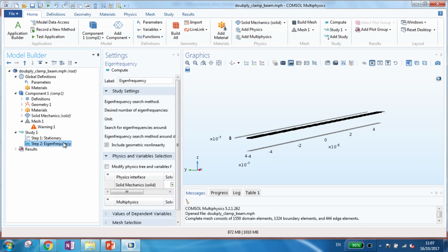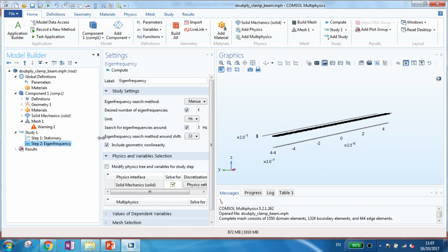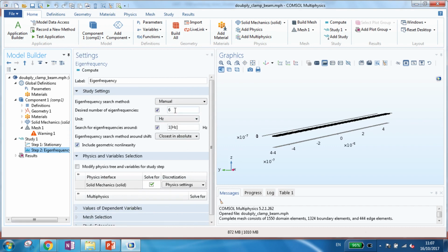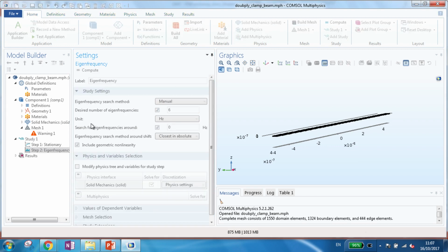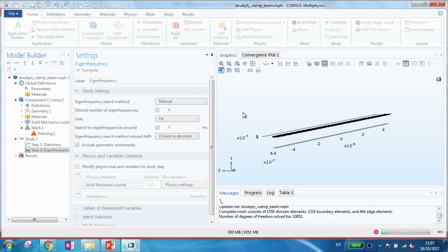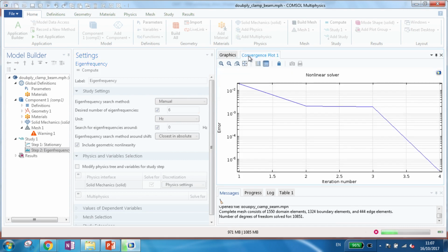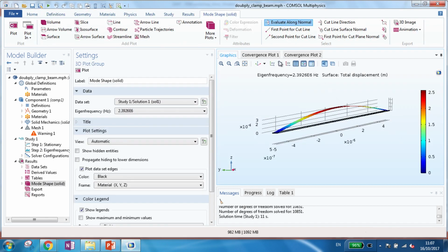results. So I just hit the simulation. You do the same thing. So now if you look, there are two solvers. First would be the nonlinear solver. It reached. So if you look at the convergence plots, guys, here, the one convergence plot will be for the nonlinear solver. It's reached. Then it starts the convergence on the second, which is the eigenmode solver. And it uses the values calculated for the first as the initial value for the second study.